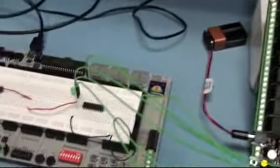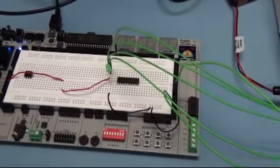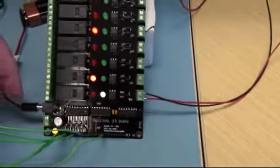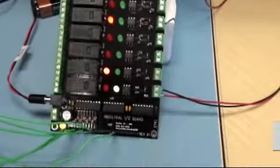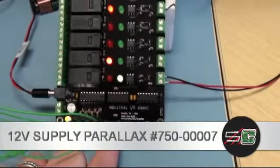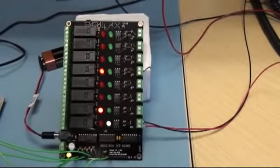And here's the PPDB set up with just some jumper wires to provide voltage and the signals to turn the relays on and off. The relay power is actually coming from a 9-volt battery right now. I just had one handy, but you can use a 12-volt wall adapter that we sell. And the center pins here aren't connected. Those are the serial interface, like a SPI type synchronous serial bus.